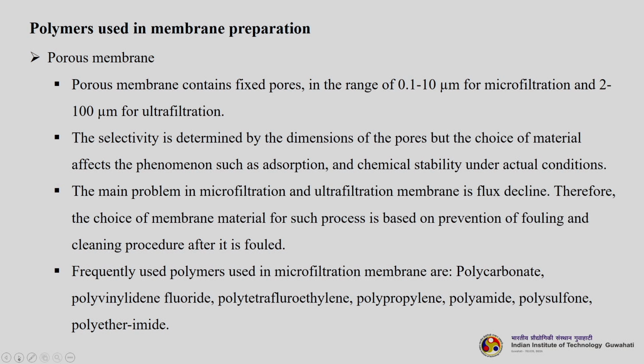The main problem in microfiltration and ultrafiltration membranes is flux decline. Okay, this we have discussed many a time. We will be discussing it again when we discuss microfiltration and ultrafiltration in detail as processes. Therefore, the choice of membrane material for such processes is based on prevention of fouling and the cleaning procedure after it is fouled. You do anything, the membrane will be fouled. So, if you choose a membrane material properly, one that is less foulable and easily cleanable, that is always better for a microfiltration and ultrafiltration system.